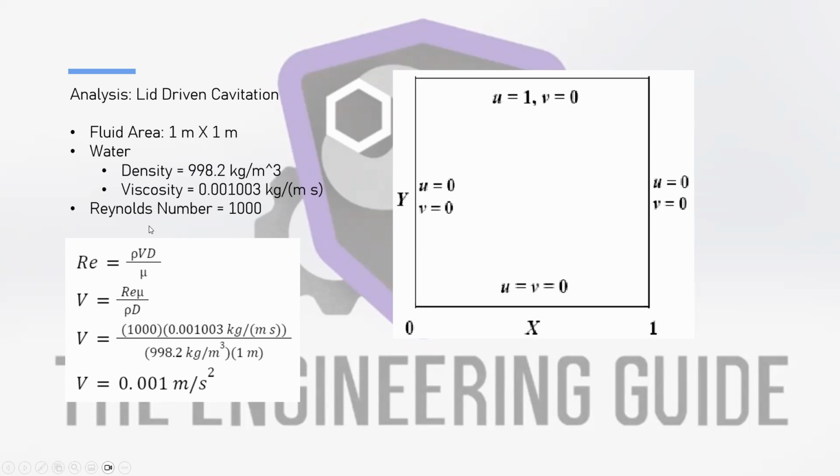And we're going to solve this problem to have a Reynolds number within our cavity of 1,000, which, as I mentioned before, if we know the relationship of the Reynolds number, it is the density times the velocity times the length of our domain divided by the viscosity. If we rearrange this, we can get the velocity of our top wall that we need in order to get the Reynolds number of 1,000, which in this case can be calculated to be 0.001 meters per second.